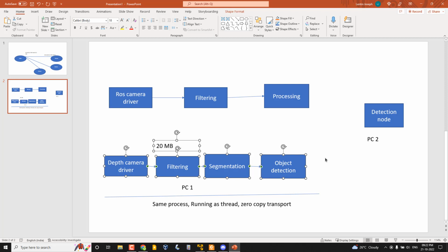It will mainly work on the same PC, because the technique that we are using in Nodelets is the shared pointer. In ROS 2, we are considering all the nodes as Nodelets, but they have other techniques to communicate between different computers. If you have two or more computers for a robot, all these computers can run ROS nodes, and they are able to communicate in ROS 2.